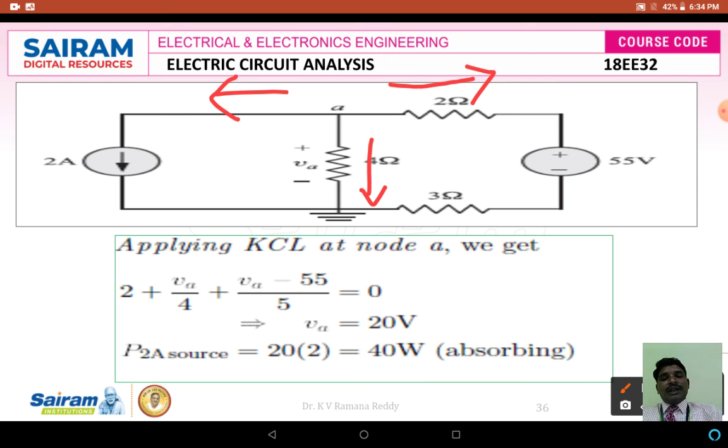With these three currents, the current moving away from the node we can write as 2, the current flowing in this direction as VA/4, and the current flowing from A to 55 as (VA - 55)/5, and the sum is equal to 0. By solving this equation, we get VA = 20 volts.